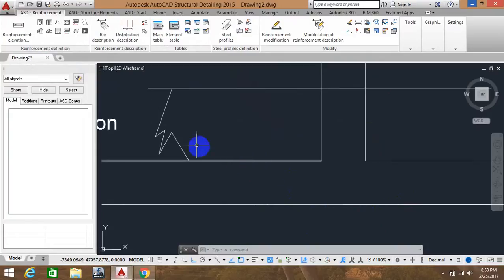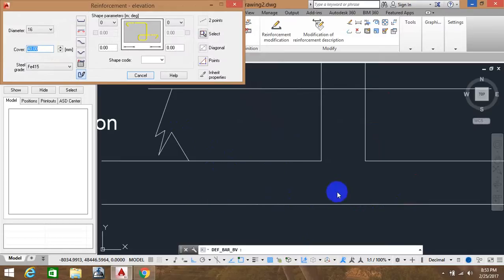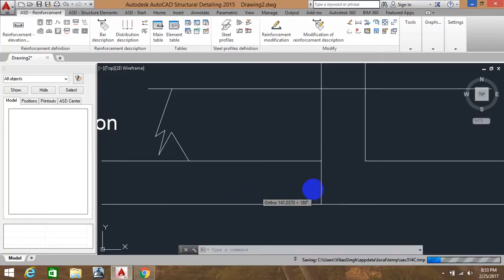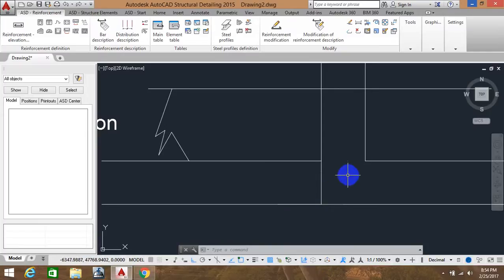First of all, one thing to keep in your mind is that whenever you are going to provide these bars, the minimum length in this area is 300. So before going to provide it, I'm just going to draw a line of 300 mm over here. This column continues to your foundation. I just forgot to show you the foundation over here, so just continue with the plinth level.